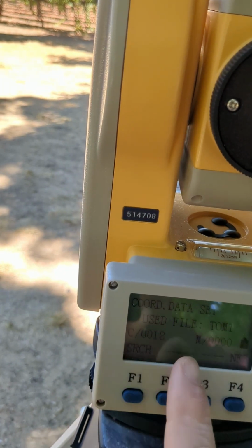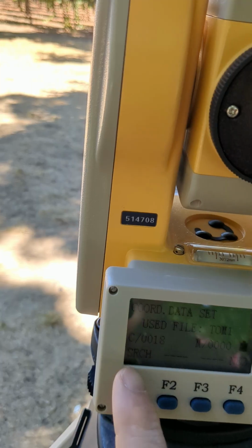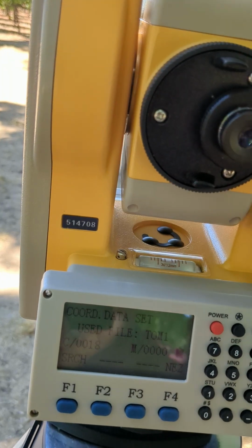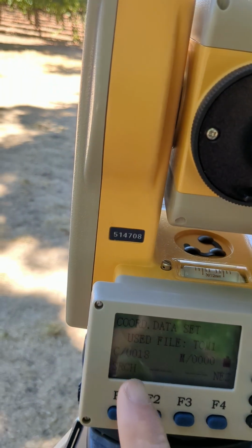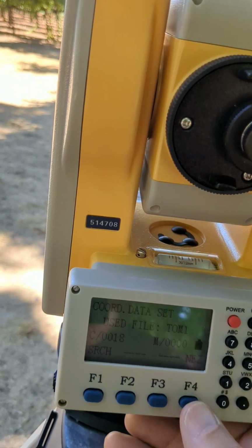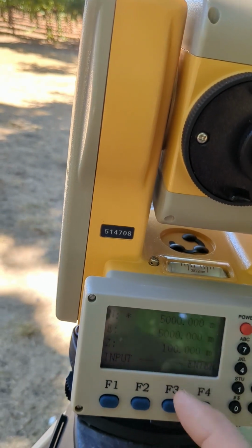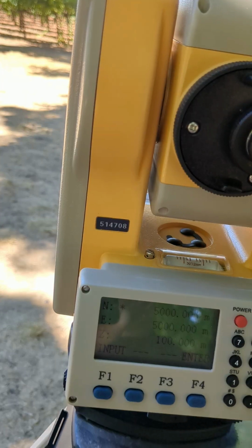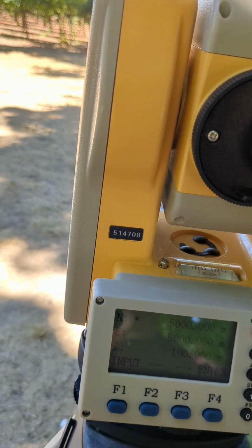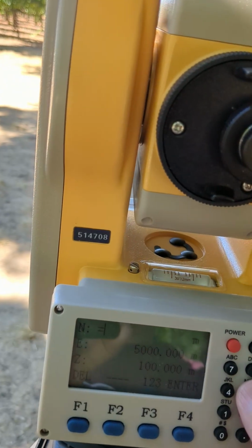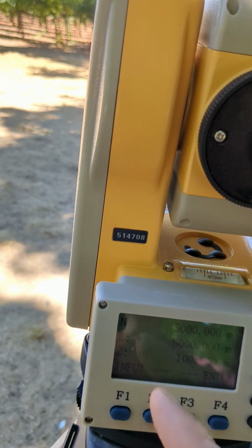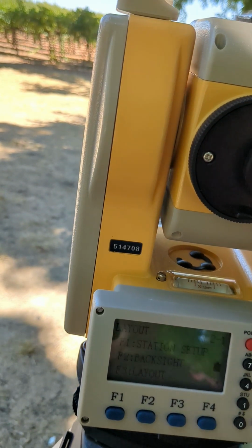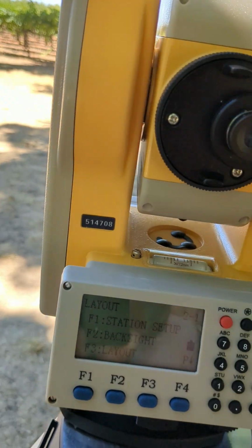I can search through them, or I can enter them manually. Search are perhaps coordinates that I already have in the field, if I was to be setting this on a spot that I had already used. But in this case, we're starting fresh, so I would hit the NEZ button to program a default NEZ. It's often in this field that we set it to 5,000 meters, and 100 meter vertical. And to do that, you follow the asterisk here, input, enter 5,000, enter, and then move on to the next one. And you go through all three that way. All X, Y, and Z. And now I'm back at the layout screen.